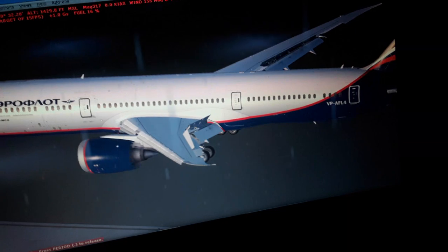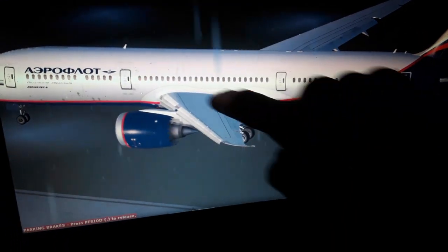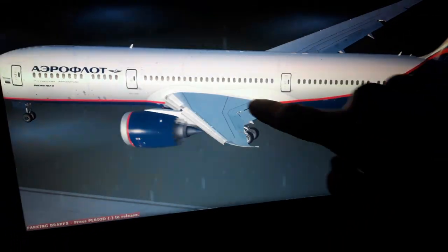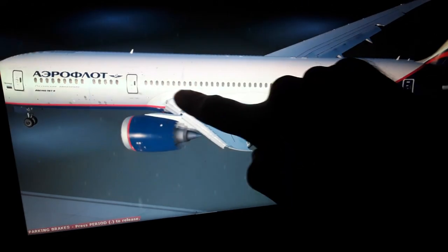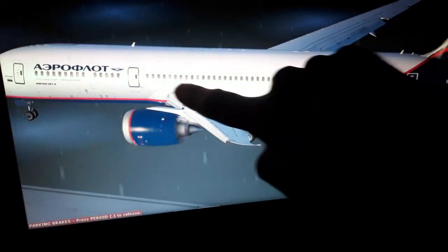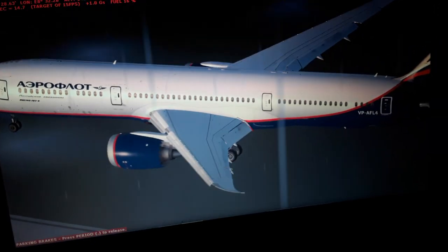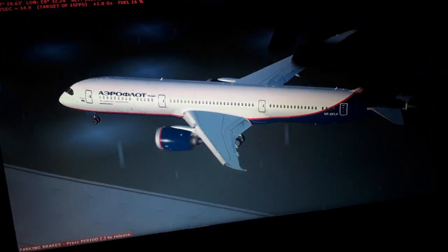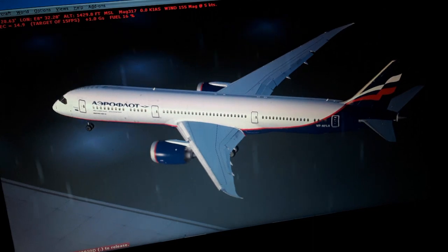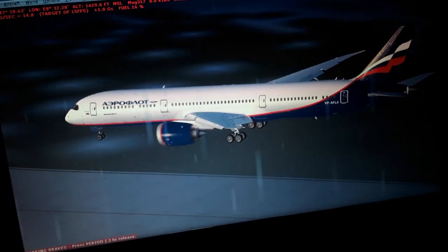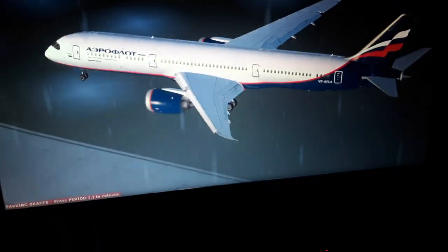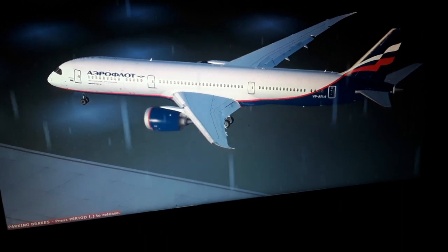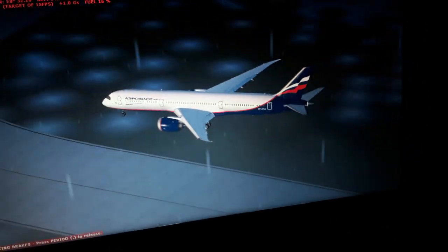And we have the top surface of the wings. You can see they have a curvature, so this creates a lower air pressure above the wings because the air is moving much faster above the wings. So this creates lower air pressure that sucks the aircraft wings up into the air. So we have the differential pressure below and above the wings. So I'm gonna show you a couple more things over here.